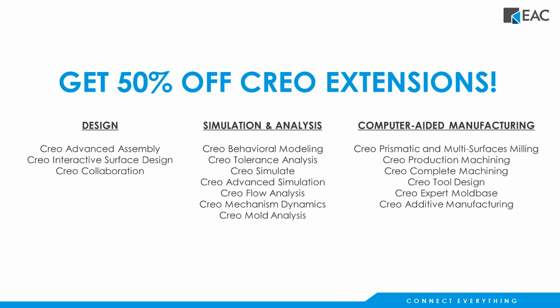In a way, it kind of is a skeleton, because your sketches now are the skeleton in a multi-body part. And if you have fairly simple assemblies, you could get by without advanced assembly. Again, advanced assembly has a lot of tools in it aside from skeletons and copy geoms, different tools to work with large amounts of data. But for smaller assemblies, it kind of serves that purpose.